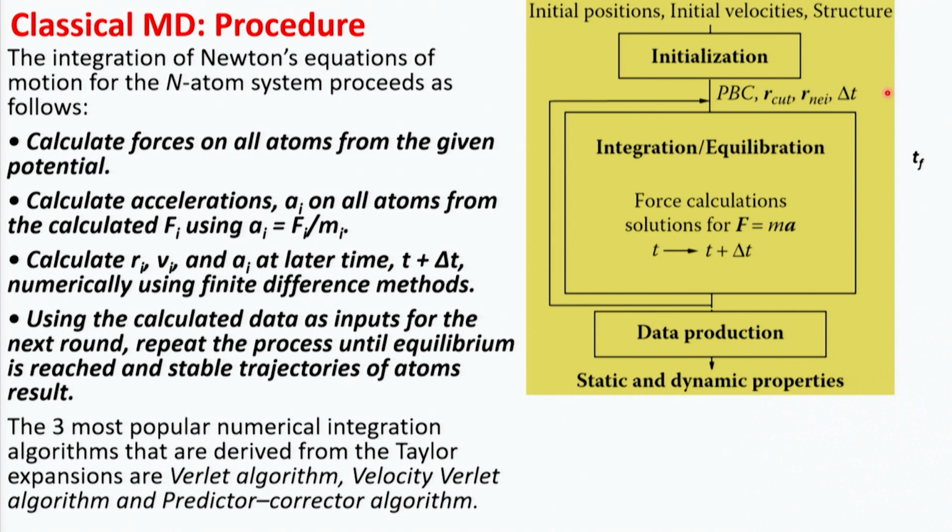Okay. So then comes the integration or equilibration step, where essentially we go for the force calculation. From the force calculation we get the acceleration, and also we use those different algorithms. Okay. Then we get the data, and from the data we can get the different static and dynamic properties. So this is essentially the flowchart for molecular dynamics simulation.